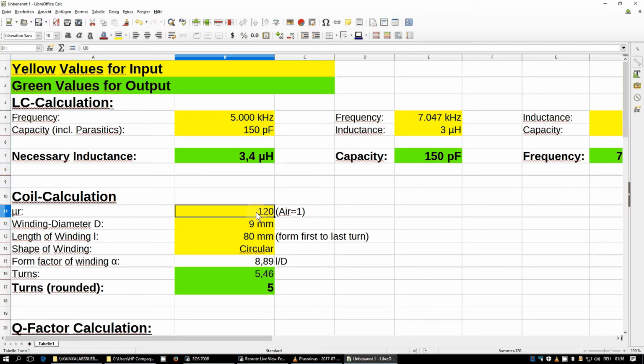And the second is the winding, although it is centered on the Ferrite-Rod, it goes to nearly the end of the Ferrite-Rod, and we have already seen when shifting a coil on the Ferrite-Rod, the permeability and the inductance that you get becomes smaller when you get to the end of the Ferrite-Rod.